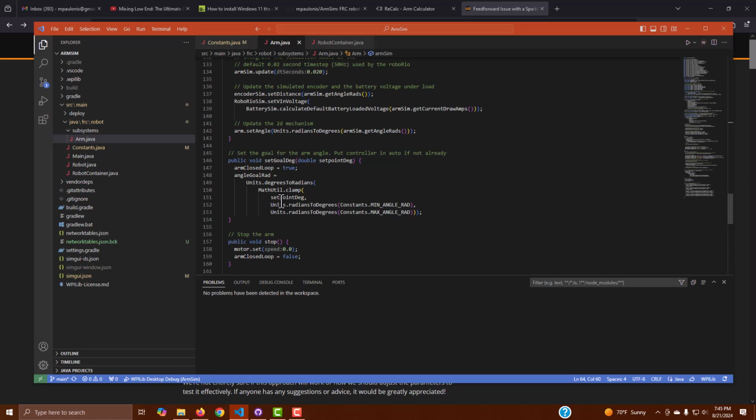And then there's a little method here to just change the goal of the PID controller. So we can just put this new set point in for the goal, and it'll pass it through. Now, goal and set point are different in a profiled PID controller. Goal is the eventual place that you want to go. It's the long-term set point, if you want to think about it like that.